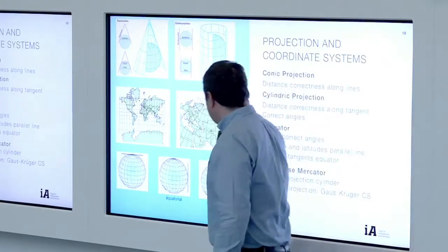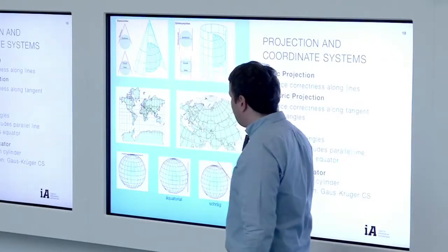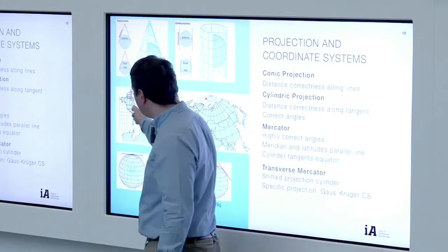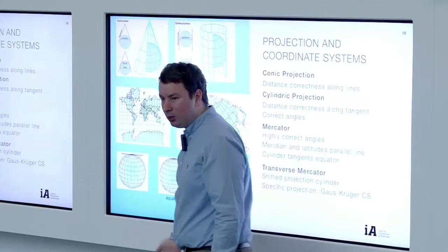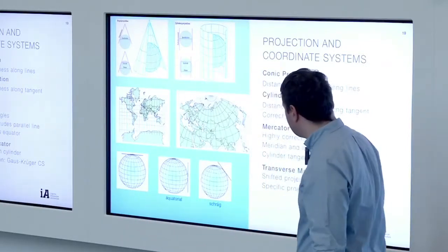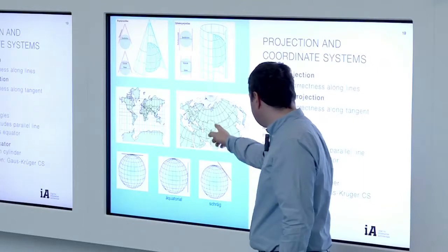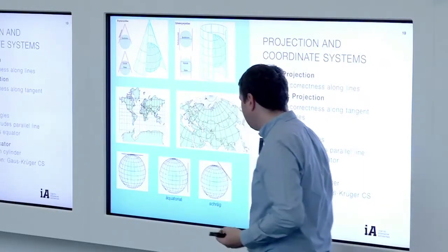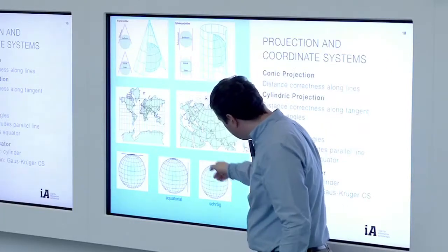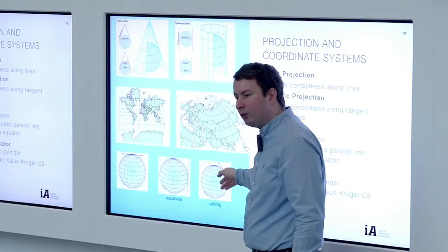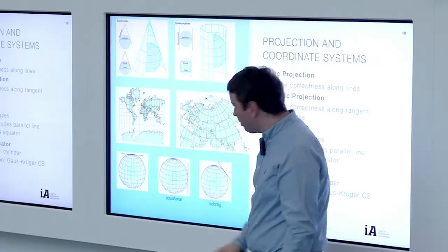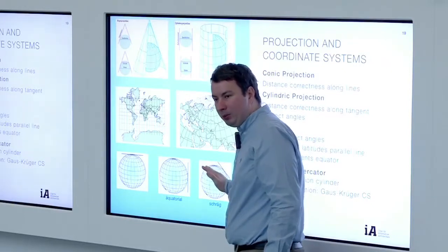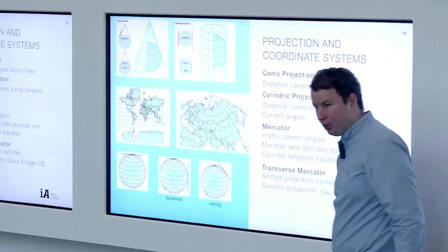With the Mercator, there are some more steps involved, but basically the idea is that you really have a rectangular grid, which is easy to operate on, to query on, and so on. And with the transverse Mercator, the idea is not that you have a cylinder, as with the Mercator, but that you have the possibility for each area where you want to have almost precise surfaces, that you just have a tangent plane placed there, and then you have that projection put there.